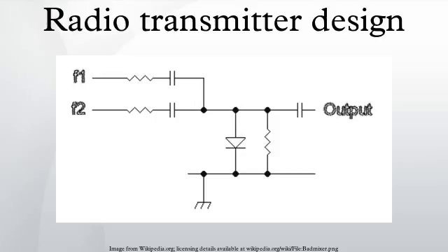For example, if 50 MHz is mixed with 94 MHz to produce an output on 144 MHz, the third harmonic of the 50 MHz may appear in the output. This problem is similar to the image response problem which exists in receivers. One method of reducing the potential for this transmitter defect is the use of balanced and double-balanced mixers.